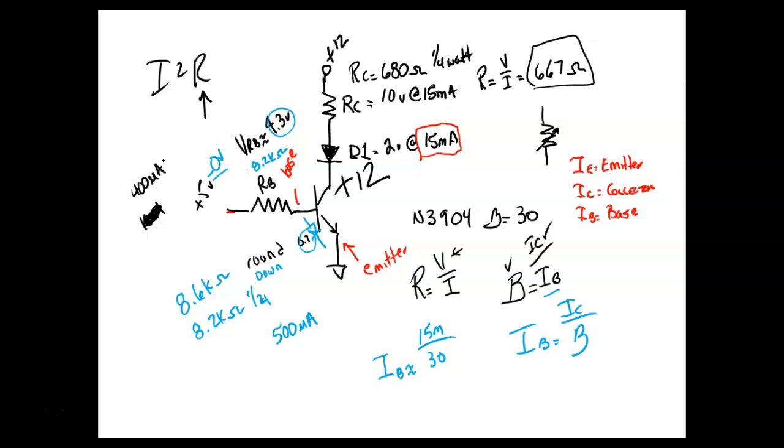We do have FETs we'll talk about. The FETs have a real high input resistance, so we'll talk about the advantages and disadvantages of FETs. So as far as computer memory goes, it's predominantly field effect transistors. If I need to drive a lot of current and handle a lot of power, then it's probably going to be bipolar transistors. So that's still the big advantage of bipolar transistors.